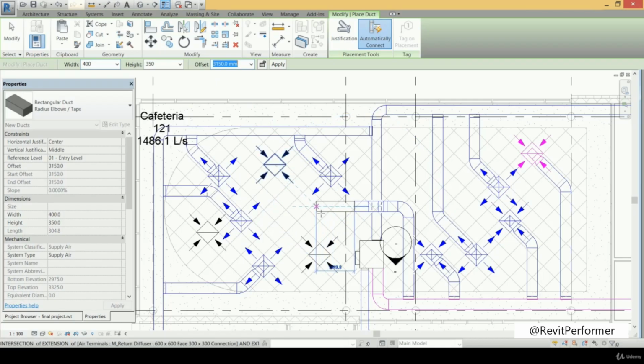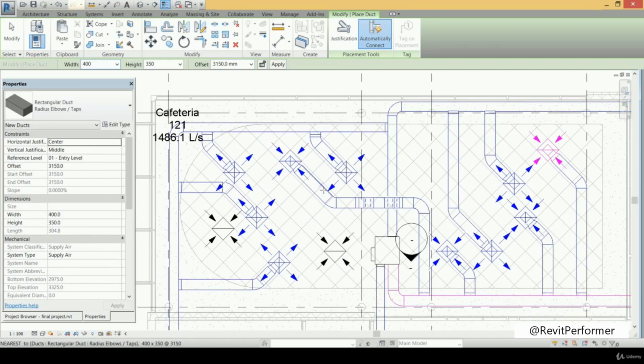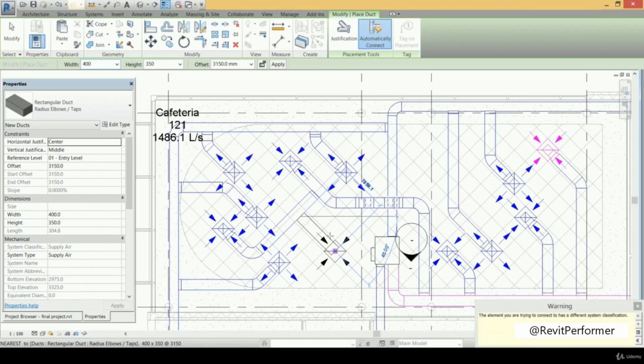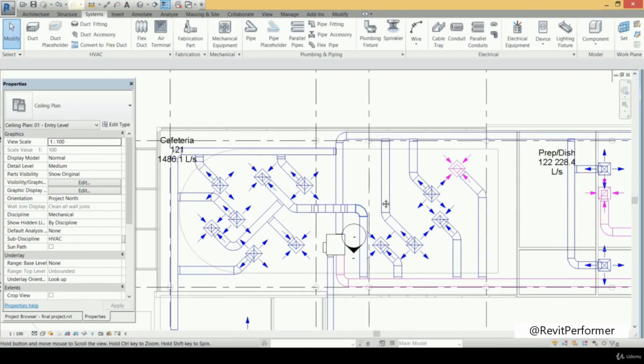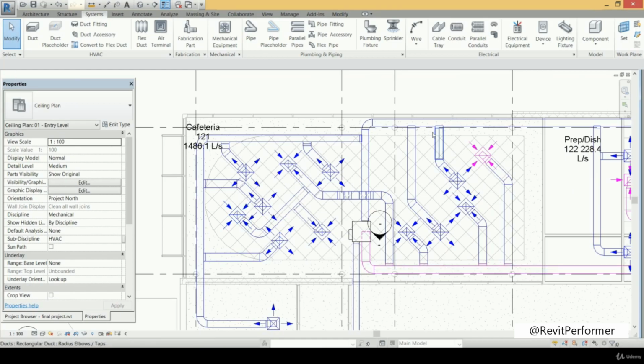And now let's move forward until that point, and then we go to that return air terminal. Very good. Now we can take a branch duct that is going here and it's going forward to that air terminal, and another branch duct that is going here and it's going forward to that air terminal. So we can go there from that point and go forward here until that point, and then we connect it to that air terminal, and then another one that is connected from that point to that point. More than great. Here we have connected the return air terminals and the supplying air terminals.